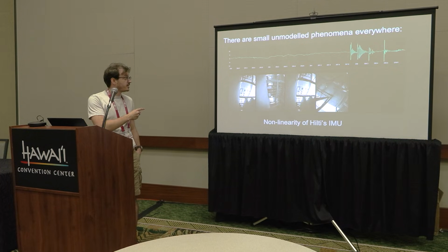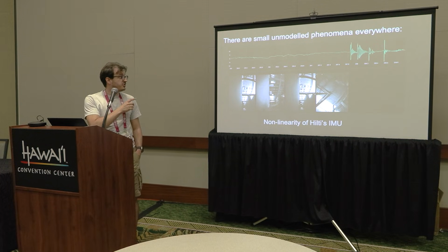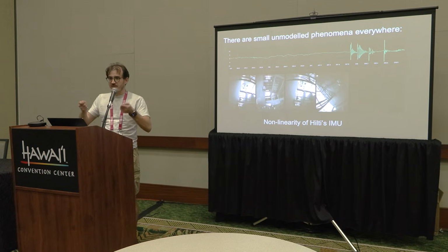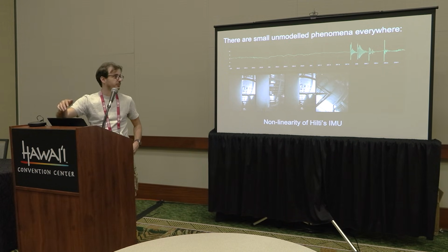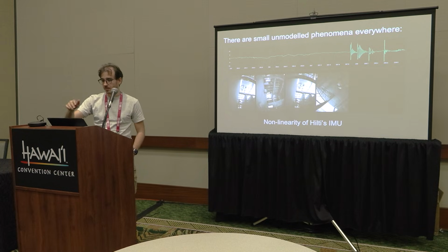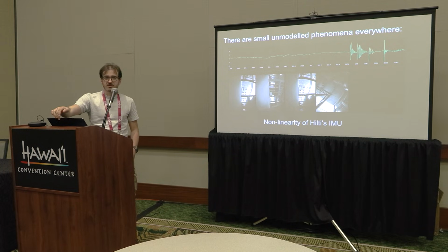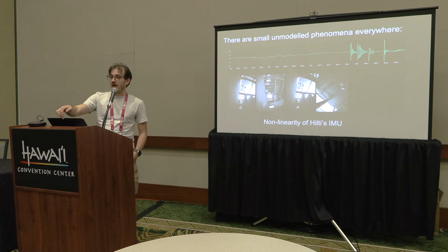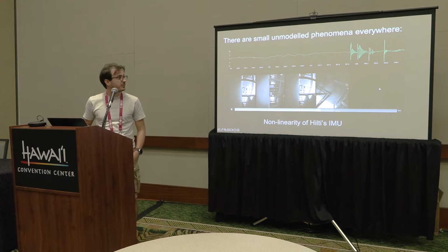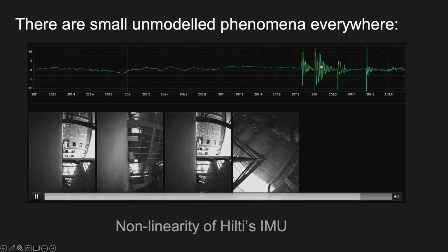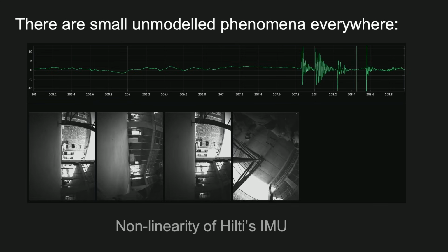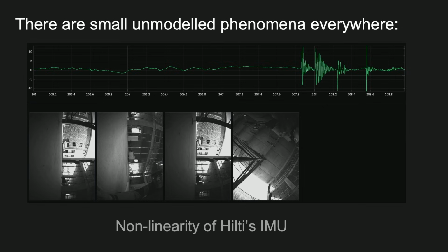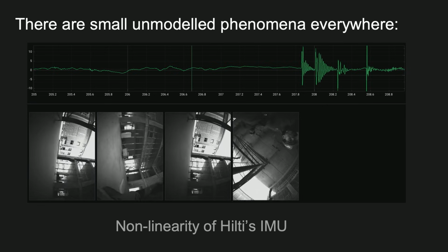The way they get position ground truth, however, is by taking the device and putting it on the surface on which they have a marker that they previously localized at centimeter accuracy. But when they do that, that induces a shock on the IMU. And for a few hundred milliseconds after this shock, the IMU depicts some kind of oscillation that I don't think is physical. I think it is more due to aliasing, or maybe a mechanical damping on the IMU.